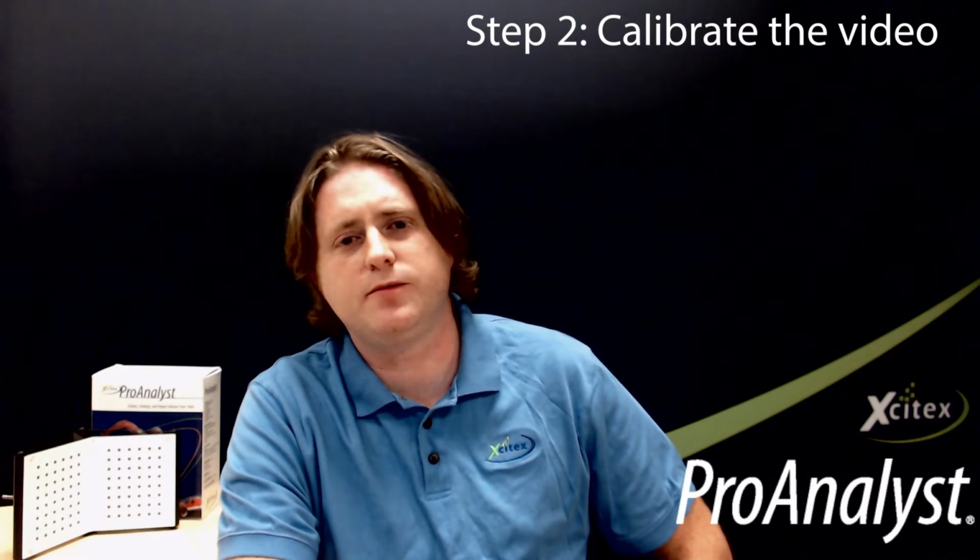Step 2. Calibrate the video. To extract information from the video, we need to calibrate the video within ProAnalyst. ProAnalyst fundamentally does not know what it is looking at. It can't tell if we are looking at a microscopic organism or the motion of stars. Calibration gives the software a sense of scale that it can then use to make precise measurements.